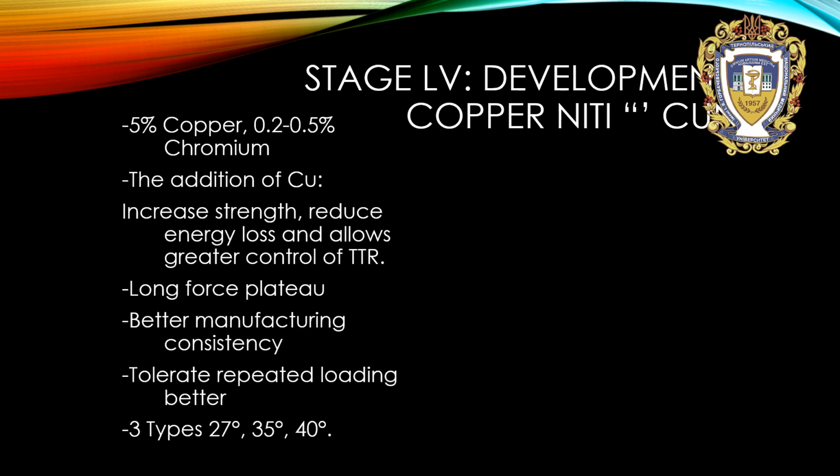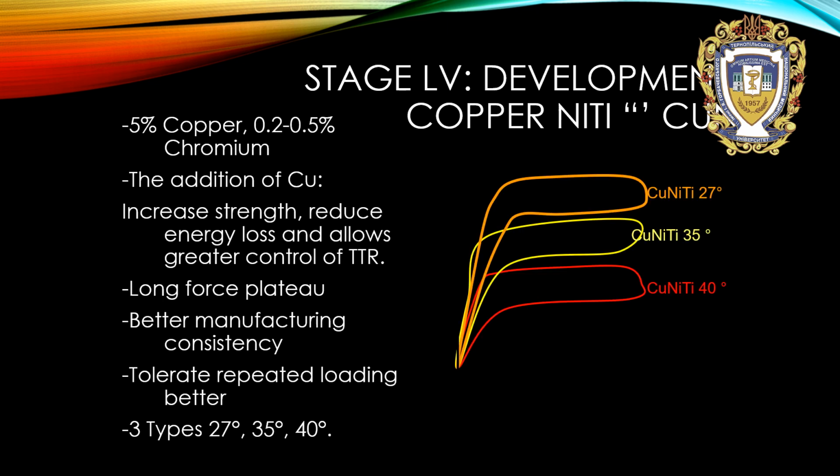Next stage of development, copper NiTi. The addition of copper increases strength, reduces energy loss, and allows greater control of TTR. Long force plateau, better manufacturing consistency, tolerates repeated loading better, and 3 types of temperatures: 27, 35 and 40 Celsius degrees, like here.